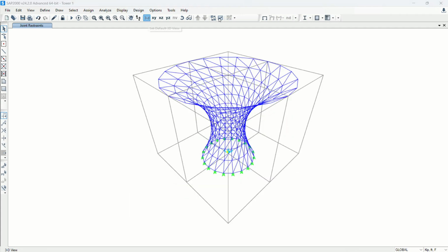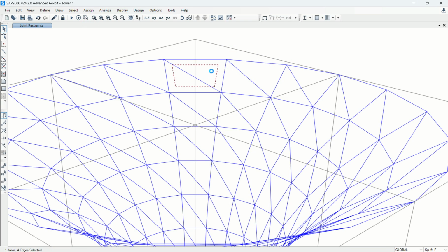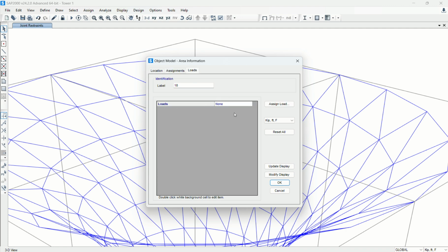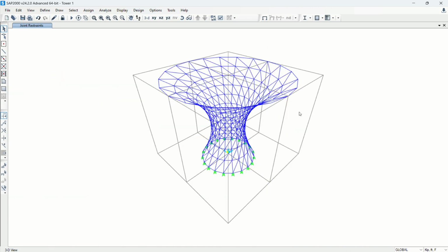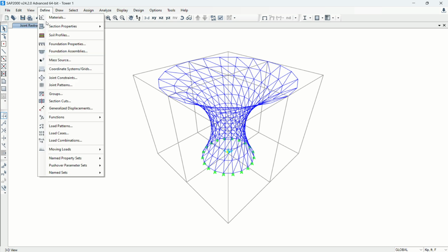Now I have the shell elements here. I assume the panel or glazing is gonna be attached to the top and bottom horizontal members, not the diagonals. Diagonals should be independent. So that's why I include the shell for the panel weight calculations for superimposed dead load.